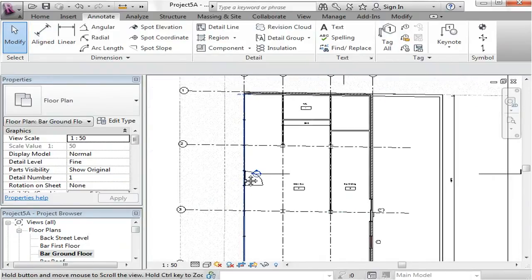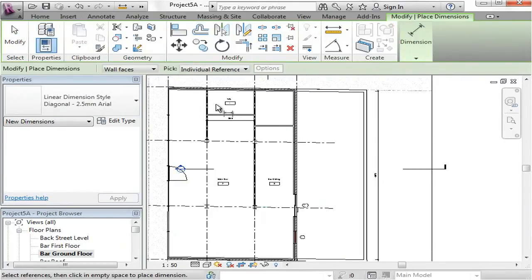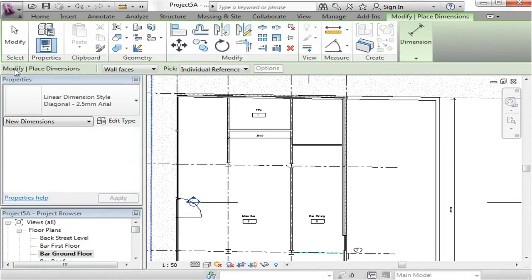Now I don't know if I have an entire wall here that isn't appropriate. Let's try the Align tool first. Now if you pay very close attention to the options bar, you'll see that there are a few options here that you can actually choose to manipulate your dimensions. Now the first one has 4 options, and basically that allows you to align the dimension lines, or more specifically the witness lines. In here you see wall center lines, wall faces, center of core, faces of core.